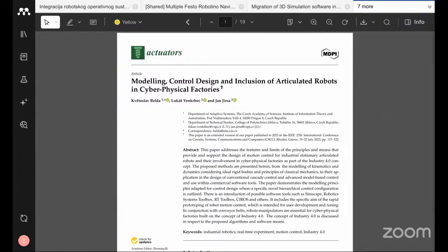So in this structure, they are dividing the control activities in multiple levels. Factory level control will decide the production task. Robot task planning means it will be like pick and place jobs. Trajectory planning means it will find the suitable path. Joint control: each and every joint has a specific position or speed, right? Motor control is to control the motor torque.